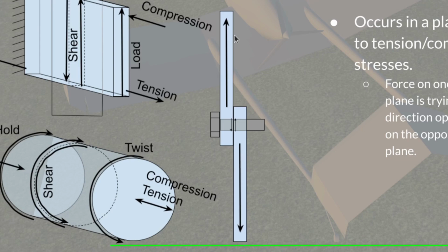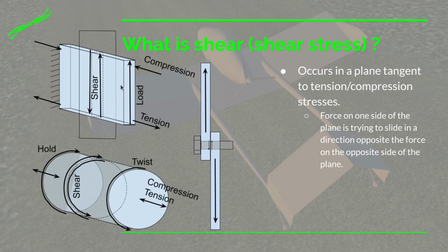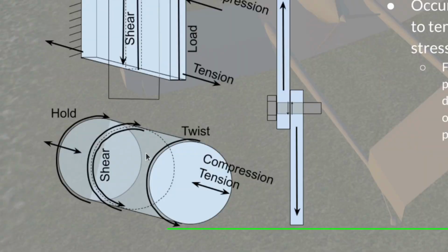Except in this case, let's say this is a blade and this is a blade on the shears, and they're open, so you'd have a gap down here. When they come together, there's going to be that plane right there, and when they start pushing on the material that was in that gap, it's going to put a shearing force on that material and try to cut it. Now we're kind of leading up to what's going to happen for shear force in beams, but one little quick aside: